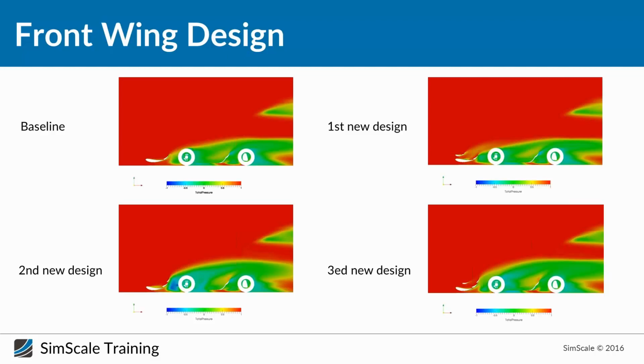Well, this shouldn't be dependent on speed. This should be independent of speed. If the wings are generating 80% of downforce, it will be the same at any speed. And I think what happens with Formula Student is it's got a huge front wing, a huge rear wing, and actually quite a small diffuser. That's coming from the regulations, I expect. Whereas if you look at a Formula 1 car, the diffuser and floor will generate probably 50 or 60% of downforce. Yeah, that's right. From the wings.